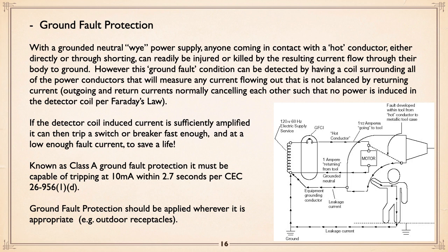What happens if that, quote, hot conductor wears against an enclosure such that the enclosure becomes that line? Basically, if somebody walks up and puts their hand on the enclosure and they're standing on the ground, they give the power an alternate path. It can either go through the motor, which is a load, or it can go through that person who put his hand on it. And with one hand, out through his heart down to ground, you can see the consequences.